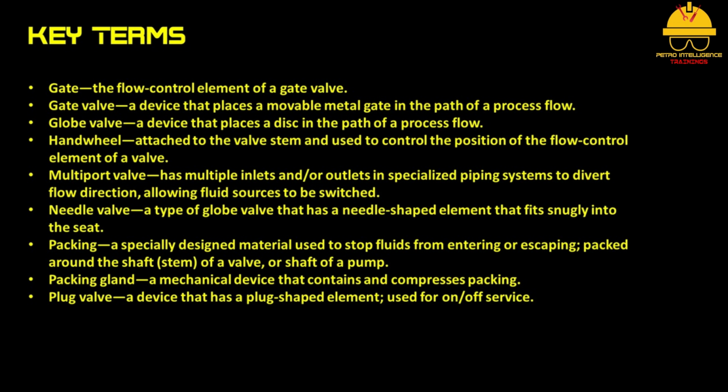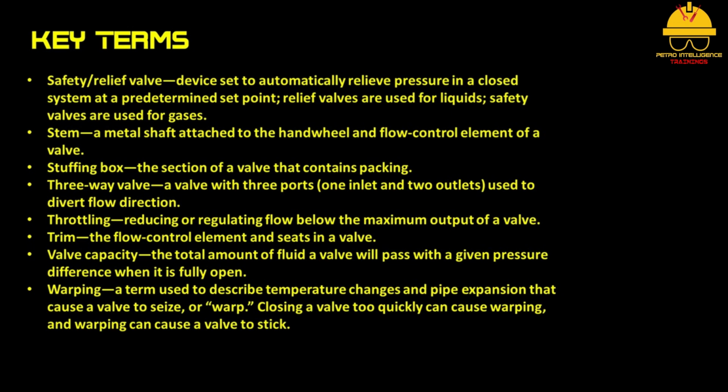Packing is a specially designed material used to stop fluids from entering or escaping, packed around the shaft or stem of a valve or shaft of a pump. Packing gland is a mechanical device that contains and compresses packing. Plug valve is a device that has a plug-shaped element, used for on-off service. Safety or relief valve is a device set to automatically relieve pressure in a closed system at a predetermined set point. Relief valves are used for liquids. Safety valves are used for gases.